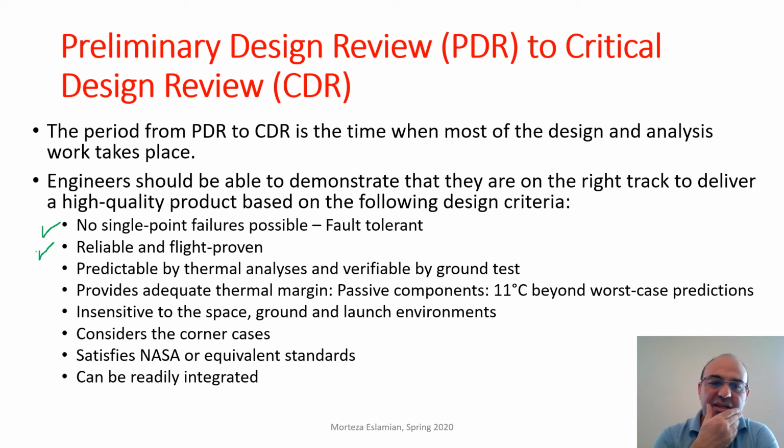They need to demonstrate that the system that they are designing has behavior that is predictable by thermal analysis and verifiable by ground test, because this has not been constructed yet, right? So at this stage, it's basically calculations and perhaps some development tests if a new solution is going to be used.